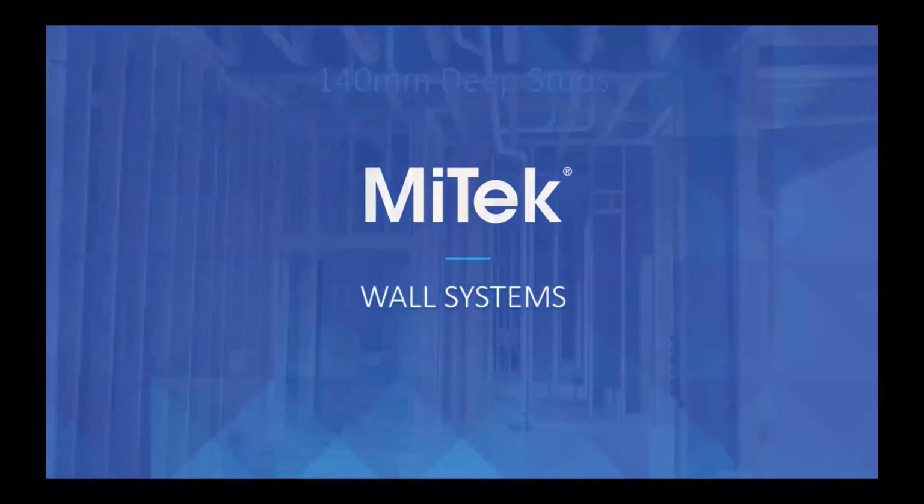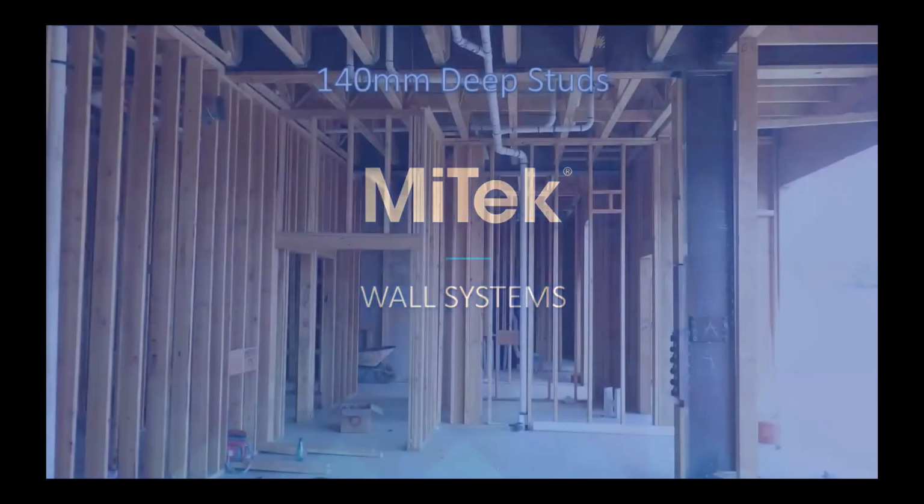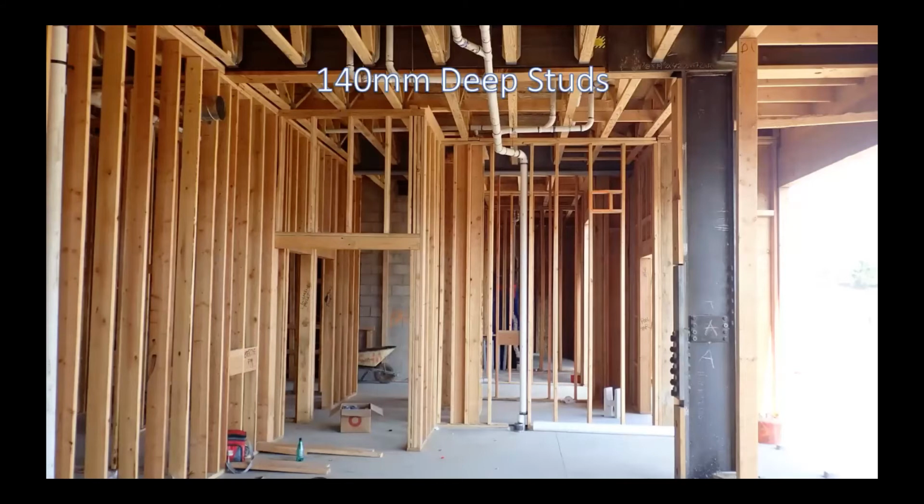Walls. What do we see over there by way of walls that we build? As I say, I'm emphasizing light timber frame construction. One thing we notice is that they're not afraid of using deeper sections. 140 deep studs is very common over there, and they will put it wherever that's needed. So if it needs to be done, just do it, and it's very effective.